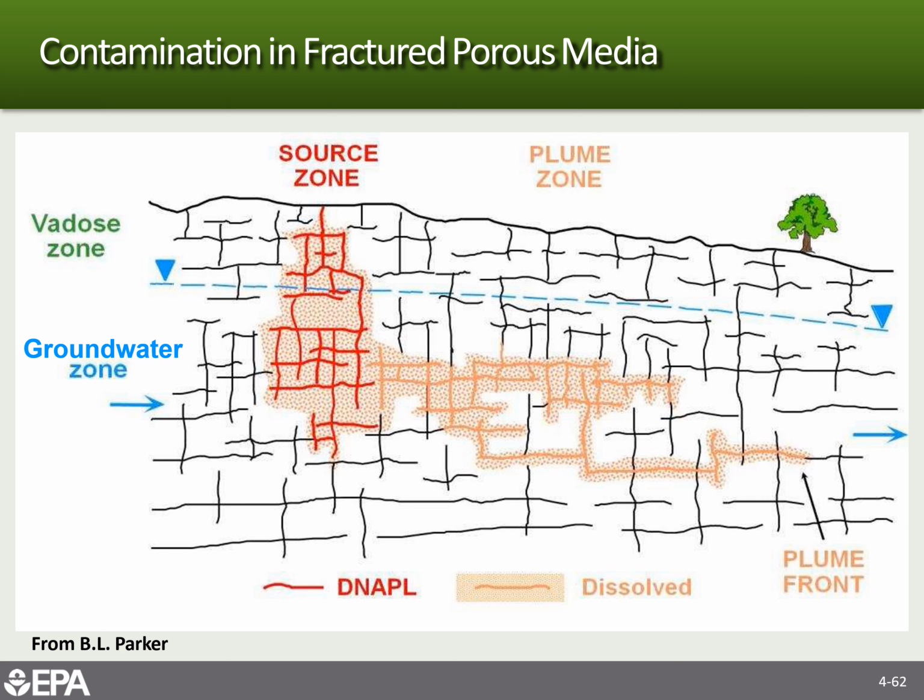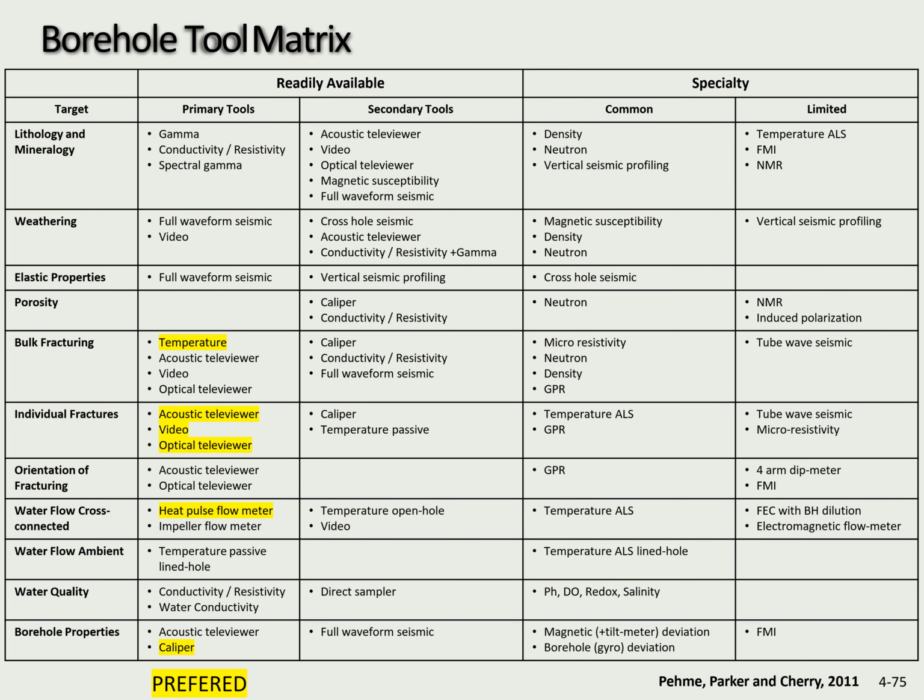Basically you need to drill some holes and run some logs down, some borehole geophysics and sampling equipment down the holes in a certain sequence before you can really understand which direction your contamination is going and what the nature of this fractured rock aquifer is, if it's metamorphic or if it's a sedimentary, like a fractured limestone. It's generally the most difficult zone that we have to deal with in our profession.